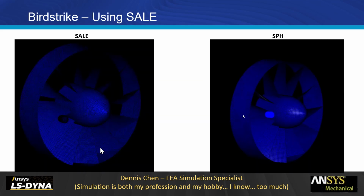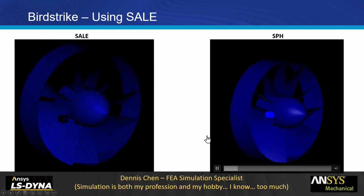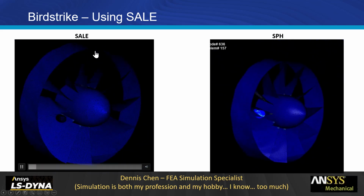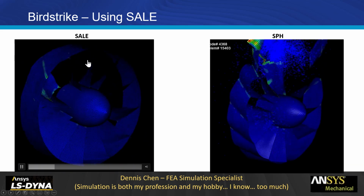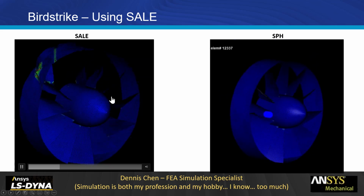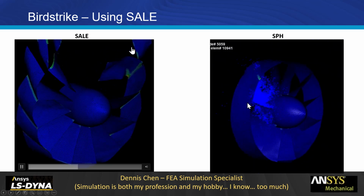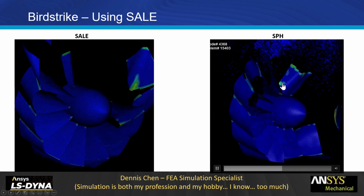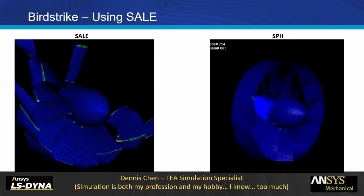All right, today let's look at how to do a Birdstrike analysis inside LS-Dyna with SALE. This is actually one of the SPH runs I did with Birdstrike. You can see compared to the SALE, they look relatively similar. The difference between the two is that SALE uses a multi-material group to model the fluid interactions with the structure, whereas SPH uses essentially particles, right? So I did a SALE model for a sloshing problem last time.